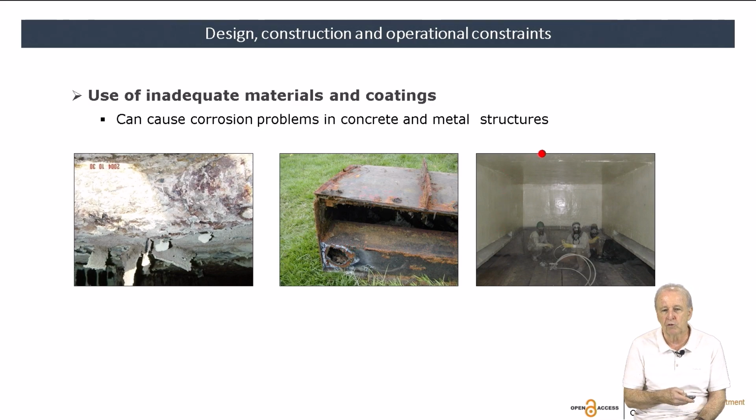And here, one solution, what can be done? This is one gas chamber in concrete, but the proper, adequate coating was used here to protect this concrete structure. And this coating was made 20 years ago. I entered this reactor recently, and I can say that the protection is still there. It's working properly. So there are solutions.